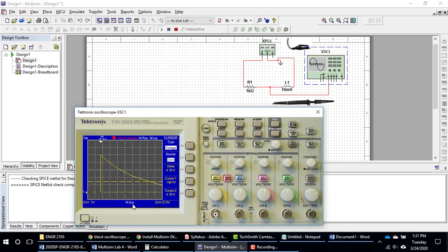I believe the time constant for this circuit is 10 microseconds, so if you can, set it to 10 microseconds, and then put the horizontal position so that it starts on a vertical line. So each time you pass a vertical line now is one additional time constant. Go ahead and complete the resistor inductor portion of the lab and return to this video.